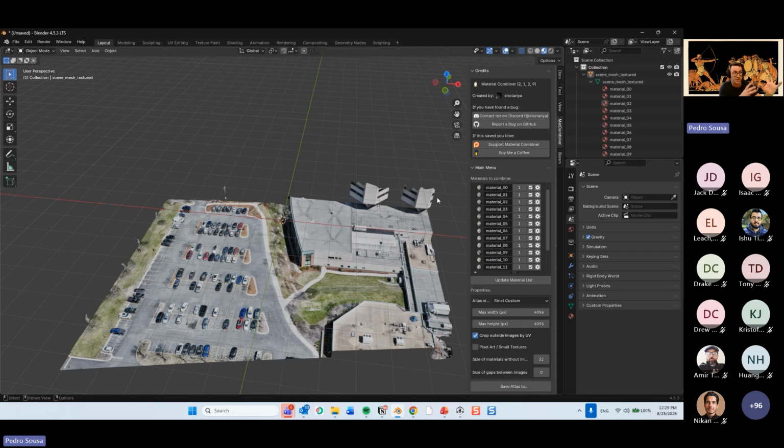We had a Python script that you go through and it would reduce the images for you. But if you don't have a huge list of materials, what you can do is go through each one of these materials and set up a custom image size, and then define over here a max width and max height.